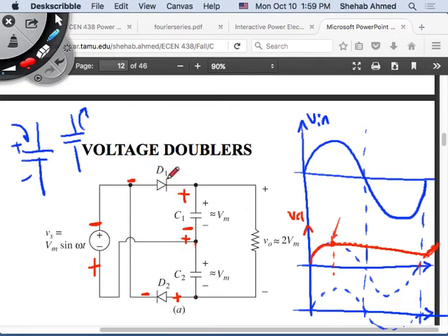So what's going to happen to this diode? This is a negative voltage, and this is charged to my previous supply voltage in the positive half cycle, which was positive. So this diode will block. This diode now conducts. So current flows from my source here. What's happening to my capacitor current? Remember now, I am pushing current into the positive terminal. I'm charging the capacitor. Now in this half cycle, I'm charging the bottom capacitor.